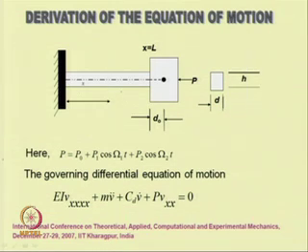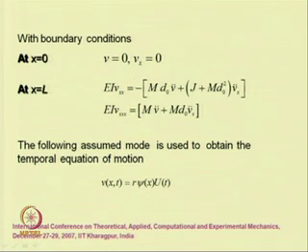Then by adding this damping term, one can have this CD V dot term, and one can add this additional term due to the axial loading. So, one can find this governing equation. This equation is the spatio-temporal equation, which can later be converted to its temporal form by applying the Galerkin method. In this case these are the boundary conditions.